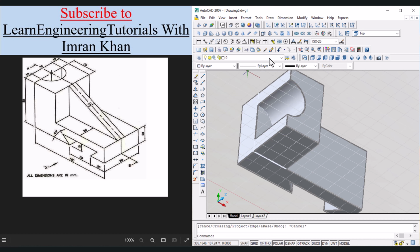Now press escape. Click on press pull, bring the cursor over to this area. We can see that the semicircle has been selected. Click. If we move in this side, it will add material, and if we move in this direction, in the negative direction, it will remove the material. So if we click over here, we can see that the material has been removed.